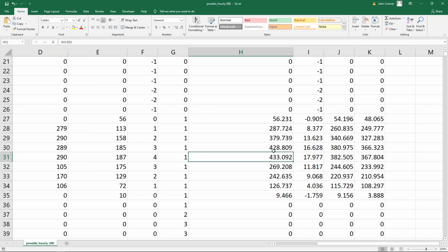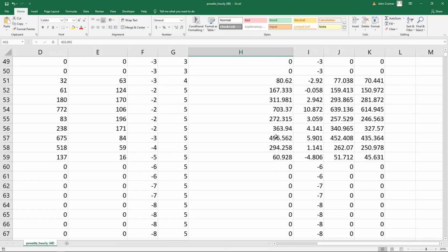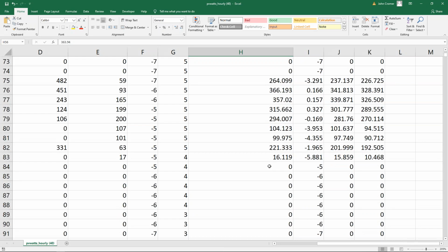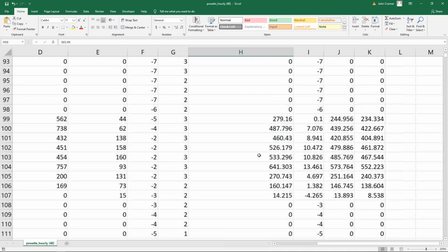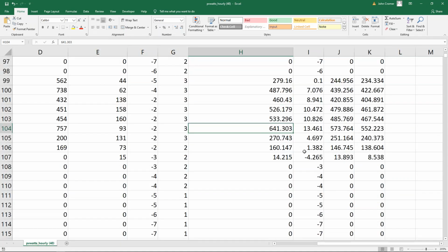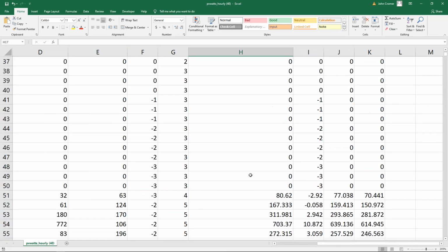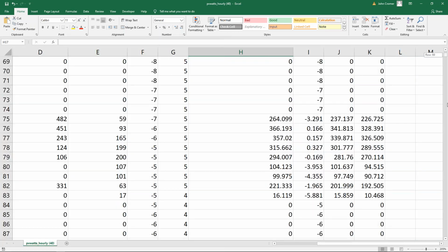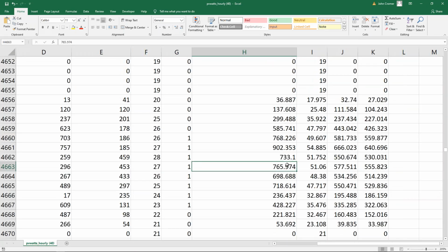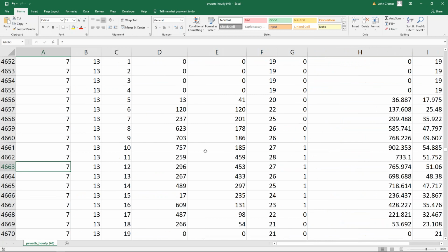But here on this winter day, it only gets up to 400 watts per meter squared, or 360 watts per meter squared, and that's only 30 to 40% of 1,000, and it'll only produce 30 to 40% of 1,000. So this winter condition, well, here's a sunny day in winter where we get up to 640 watts per meter squared. But just to move the discussion along, let's scroll down this PVWatts raw data.